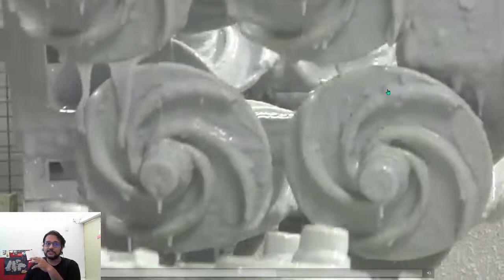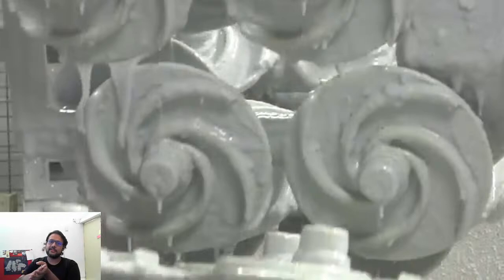Okay, so first you coat the wax tree in a thin layer of mud, and you coat it again with a slightly thicker layer. Layers are added, and it is completed with a powdery form called stucco. Think about what happens: the wax pattern is coated in subsequent layers with this material, which will become ceramic when it is fired.